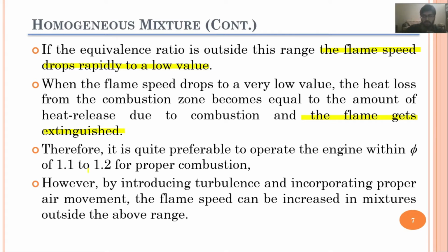However, this is another very important factor: by introducing turbulence and incorporating proper air movement, the flame speeds can be increased. And this introduction of turbulence and proper air movement depends only upon the cylinder design, the combustion chamber design. So the design factor here is very important. We cannot ourselves produce turbulence inside an already designed combustion chamber.